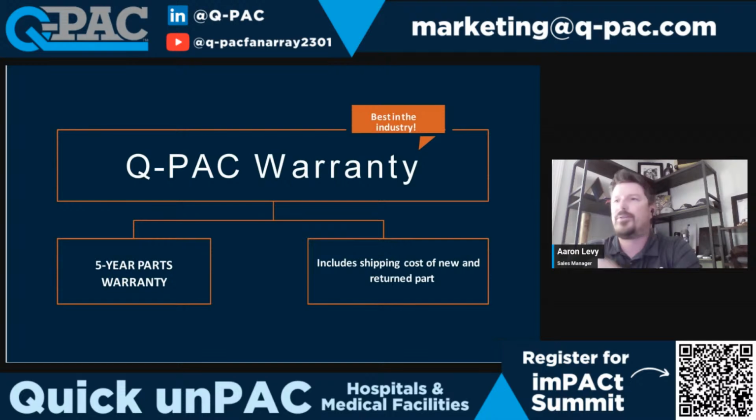And Kurt is posting that in the chat. Okay. All right. Good. Nathan also asked, while Kurt's answering that, will the premium controller provide BACnet alarms when any of the fans fail? Yes. On a premium controller, you'll get individual fan alarms. It'll tell you exactly which fan has failed, not just at the display, but it'll read it back to the BMS. It'll even give you a code of what particular failure that is.